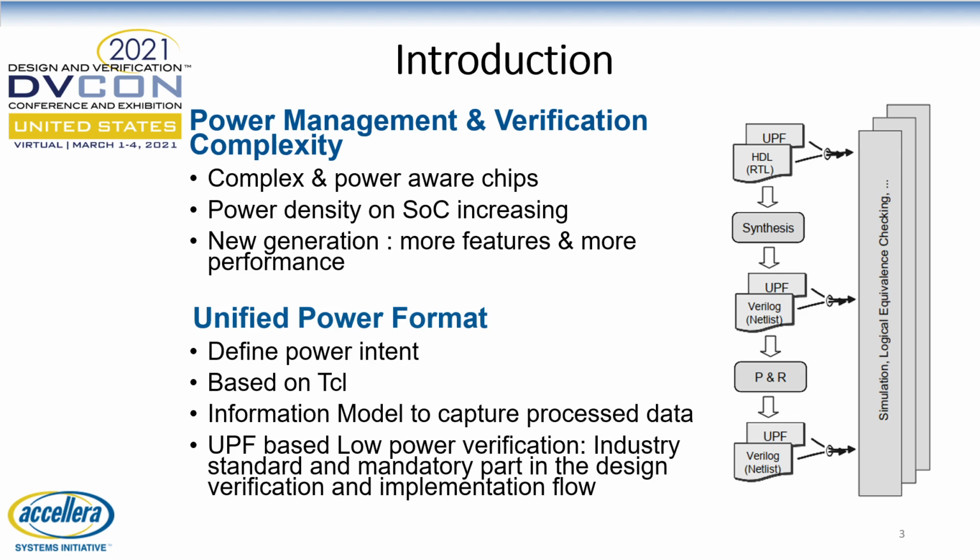Simulation tools can read the HDL and UPF design input files and perform RTL power aware simulation. Synthesis tools can read the HDL input design files and produce a netlist. The tool or user may produce a new UPF file set that combined with the netlist represents a further defined version of the same design. Place and route tools read both the netlist and the UPF files and produce a physical netlist, potentially including an output file.